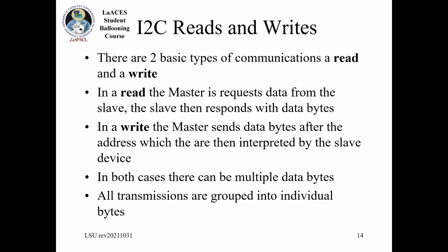So there's going to be two versions of communications, like I said, depending on what the master is trying to do. It will either be doing a read, which is where it's basically asking one of the devices to send it data back to it, or it's going to be a write, where it's going to send data to one of the devices so that they then do something with that data. But any kind of I2C communication is going to be one of these two things.